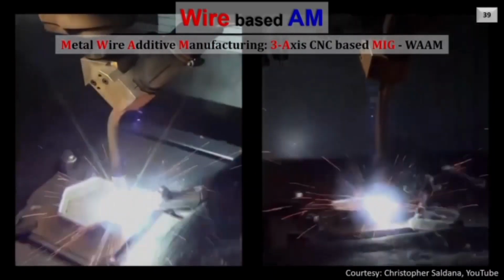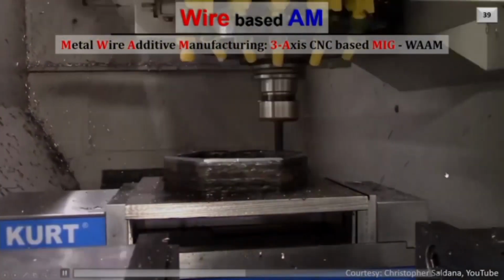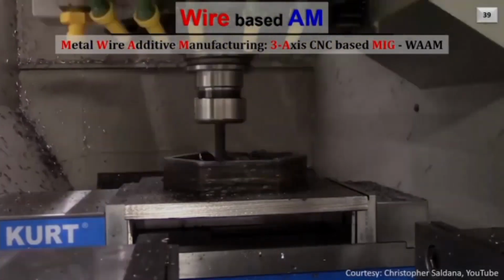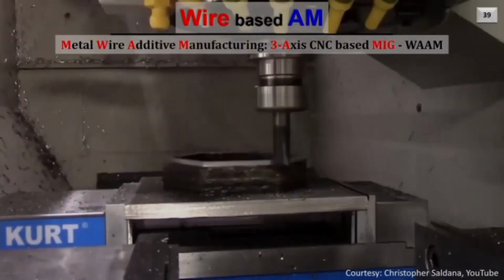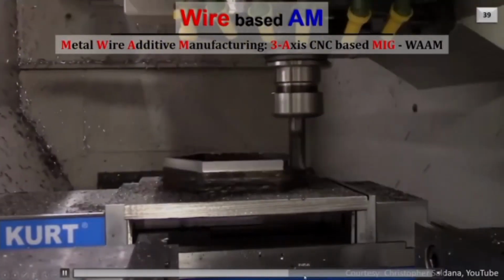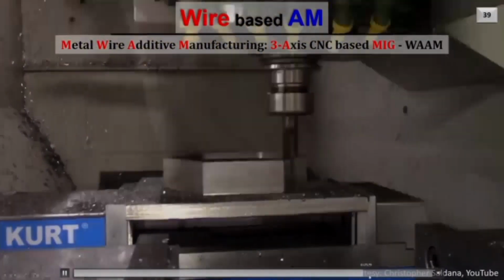As it is a retrofitment on a CNC machine itself, machining can also be performed simultaneously. Such processes are called hybrid wire arc additive manufacturing processes. So here we first deposit the near net shape of the part and then we finish mill it on the same machine to obtain the final finished object.